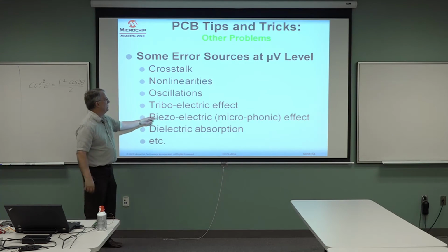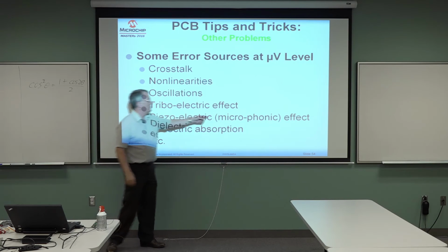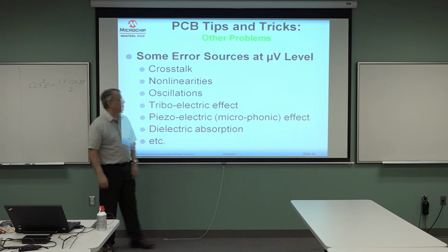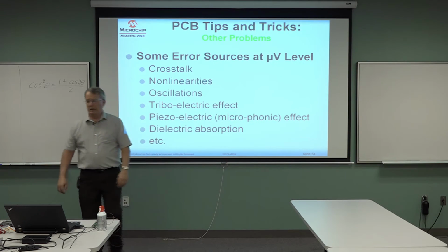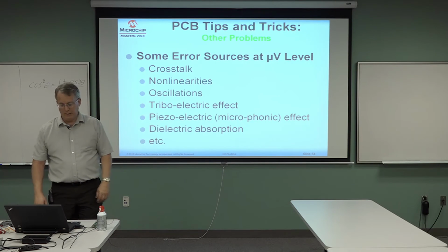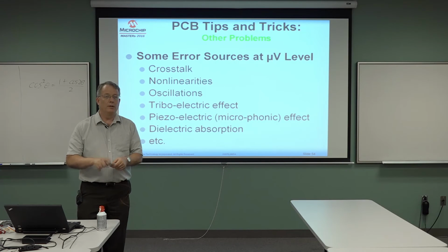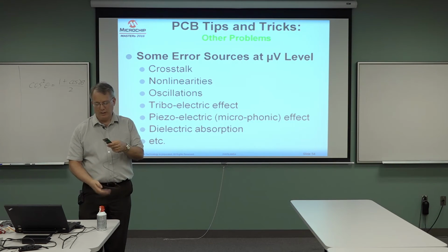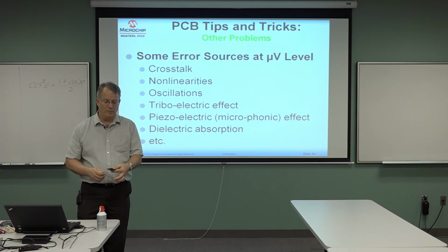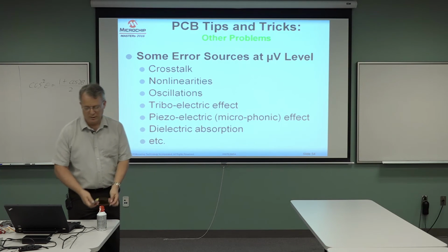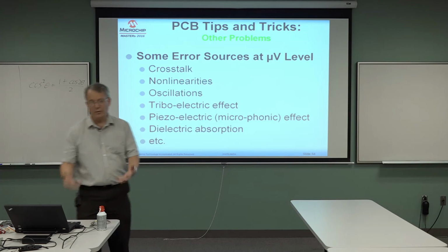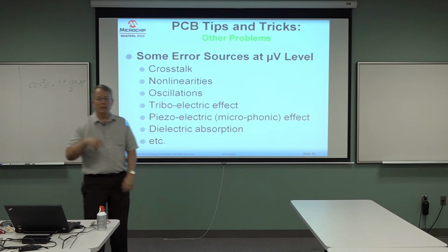Another effect is the piezoelectric effect. When I started, it was more common to call it the microphonic effect. Basically, if I take a board and I tap on it, every ceramic capacitor on the board that's non-ferroelectric, in other words, one of the larger capacitors, is going to cause a voltage spike.